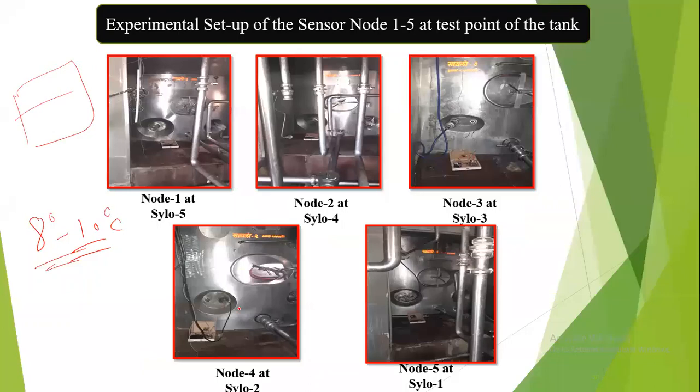So we have implemented our WSN, that is, wireless sensor network. Sensor nodes are placed; you can see here. I am just explaining this one. You can put your sensor at this tipping point. The tipping point is provided, and in that we have placed our temperature sensor, and we measure the temperature of that silo tank. The name is given, that is silo. You can observe silo tanks are given names. So these sensor nodes measure the data and transfer it towards the base station.